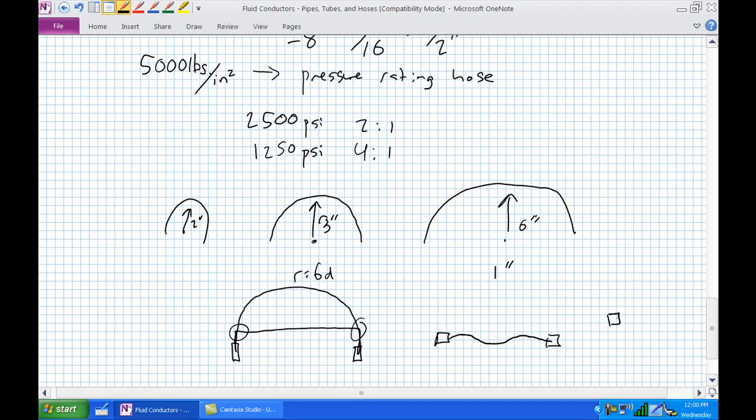The other thing you need to be aware of is those connectors, especially in earth-moving operations. They're exposed to abrasion. Sometimes there's a little spiral wrap protection there, or a sleeve or something like that. Some Kevlar sleeve that goes over those things to protect those hoses. What if you're running the hose next to an incredibly hot exhaust? Here's an exhaust pipe that's really hot. What happens if that hose comes in contact? Yeah, not good. So you want to go ahead and shield that hose with a metal shielding, or shield that actual exhaust pipe there, or reroute it.